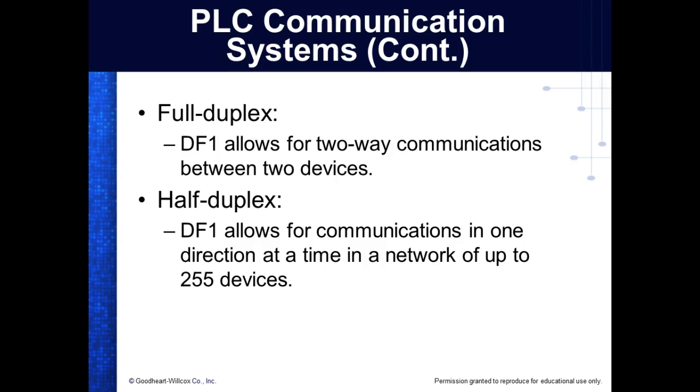You understand that? And then also there's a need to connect the PLC to other PLCs. Most of these, because if you're running an automated system, a lot of times these PLCs have got to talk to each other. Most manufacturing lines are set up in different modules, and each module has a certain task. And this module can't feed that module unless that module over here tells this PLC that it's what? That it's ready. So there's communication to that.